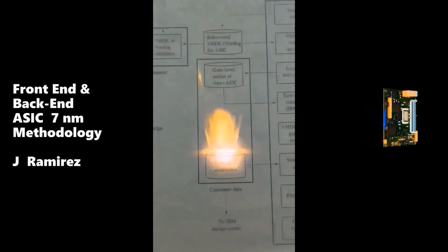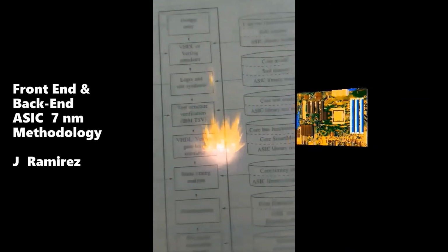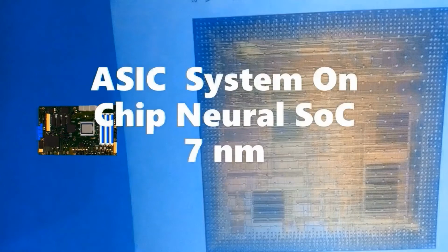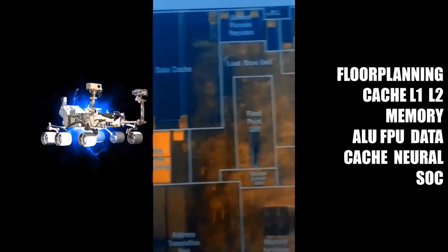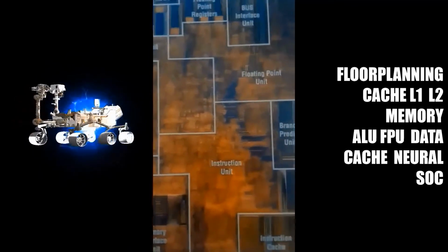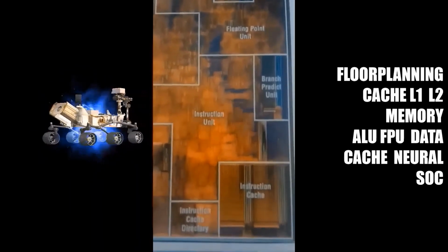Eight, generate new timing constraints for wiring on the basis of a timing analysis done using the actual clock tree and wire load and RC delay values derived from the final placement. And finally, perform routing.